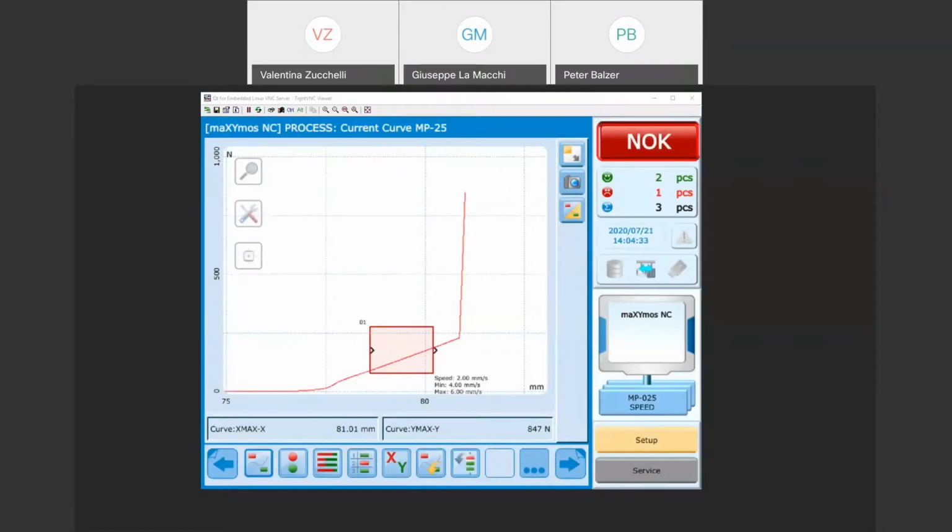The next one is also quite easy to explain. It's the so-called time window. This time window is doing nothing else than measuring the time between the entry and the exit side. In this case, I've chosen minimum is 0.1 second, 100 millisecond, and maximum is 500 millisecond. And now we needed about 380 milliseconds to go from the entry side to the exit side.